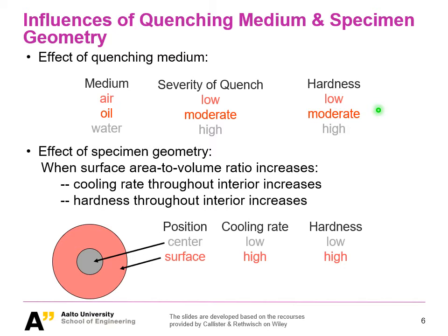Except for the quenching media, what is also important and you need to keep in mind, especially when you want to do design work in the future in terms of product or material, is whether the cooling rate is uniform. Of course it's not, right? For our kitchen knife, that is rather a simple case because it's not a large volume, it's thin and small, so you can use water to quench it rather fast and uniformly.